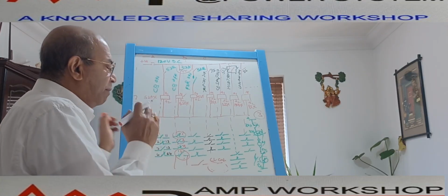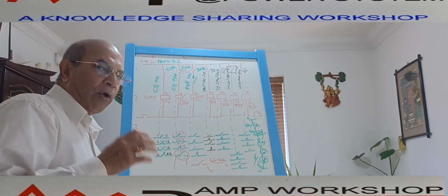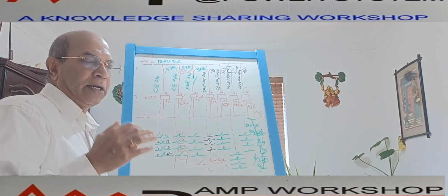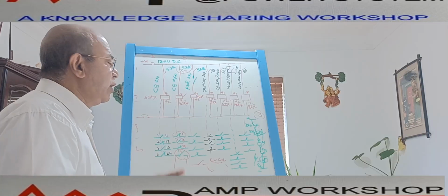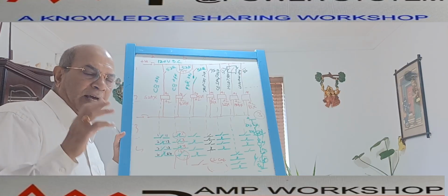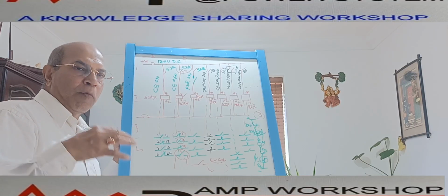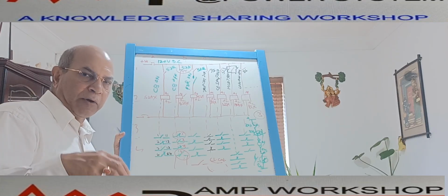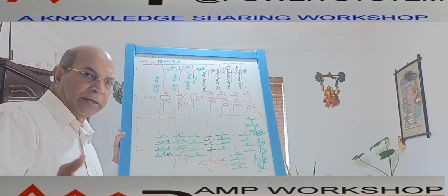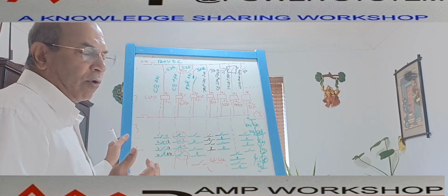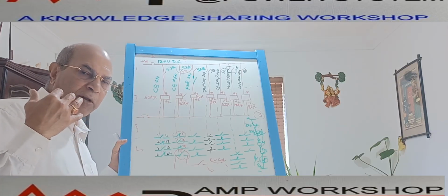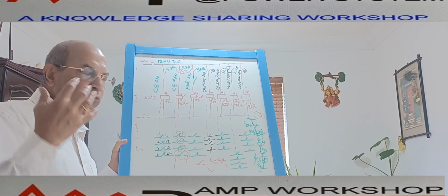In brief, we use this auxiliary relay when the main contact is not adequate, not enough. In that case, to obtain more contacts, we use the corresponding auxiliary relay. So in a circuit breaker, we mainly use auxiliary relays for multiplication of the open condition, to get more contacts for the circuit breaker open and close condition. Suppose there is a trip circuit supervision relay. That relay has a limited number of contacts. So for multiplication for the trip circuit supervision, we also use an auxiliary relay.